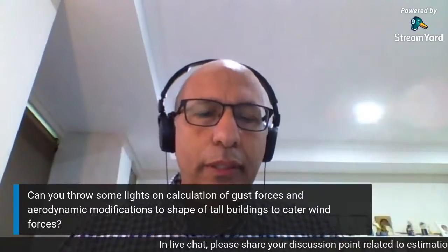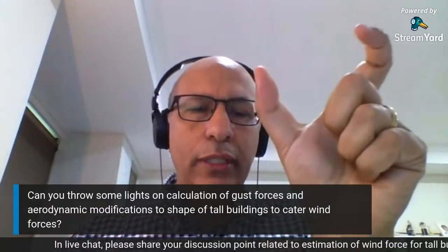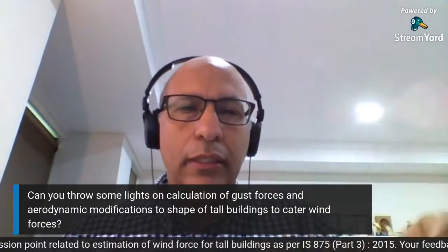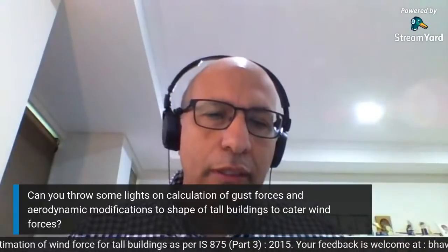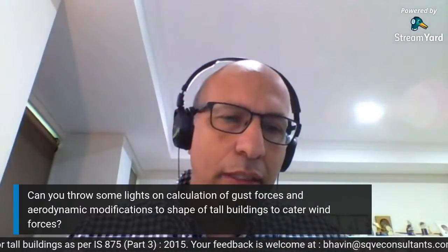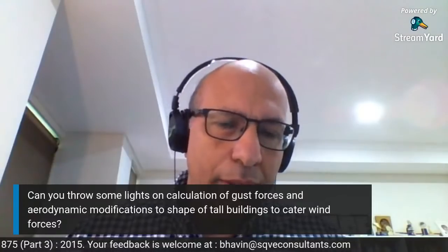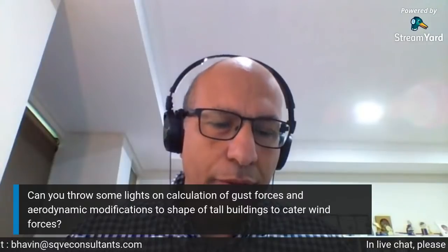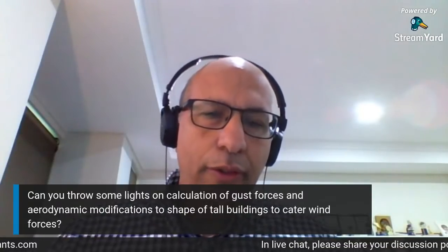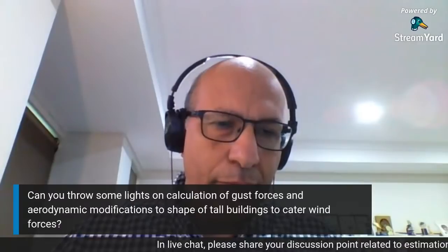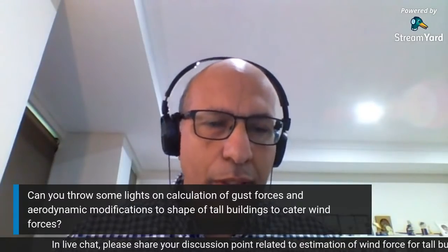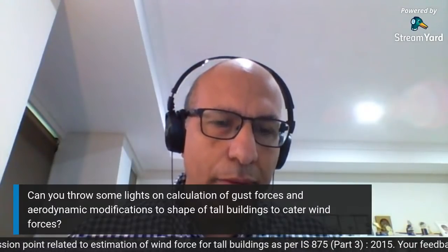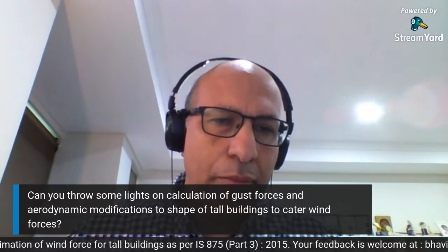So basically by providing a 10% step in the top quarter of the tower, or top third of the tower, you could potentially generate an almost 50% reduction in your crosswind. Now, the crosswind for a tall building is often more critical than the along wind. So this is a significant cost advantage. And by not doing it, it could leave the project unviable. So it's very important to look at the aerodynamic forms.